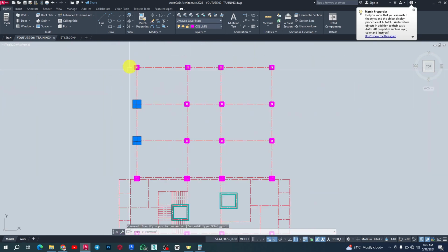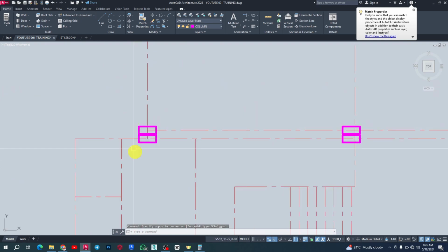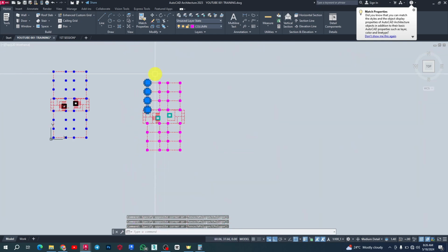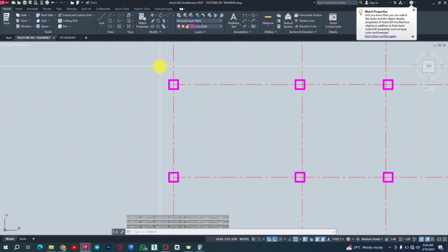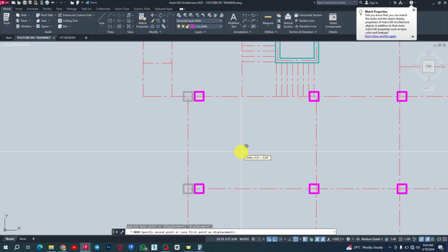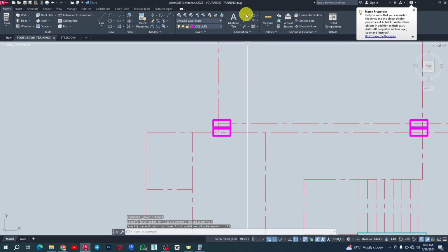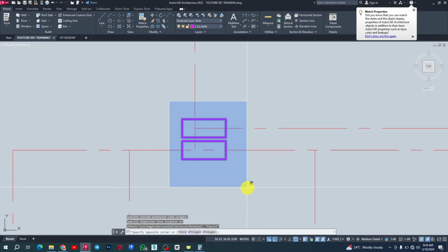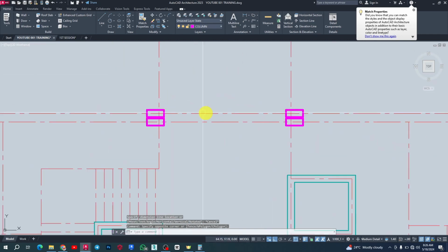This one too, we can do the same thing, bring the columns inside, right? Let me also bring this one inside. This one inside, I think they just have to get that same priority, right? Take out this one too, bring them inside. We'll have 0.125 again there. But I think it will not work with 600 columns here. This 600 here, it will not work well. So we'll have 0.18. So we'll have to take 0.05 from this one. Let me just extend this one too, so that we'll have the same thing. 0.05. Okay, so that is it.